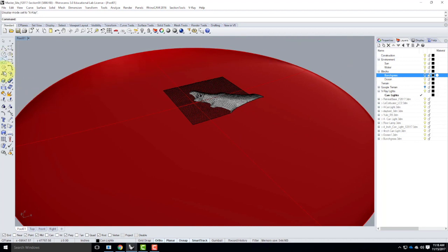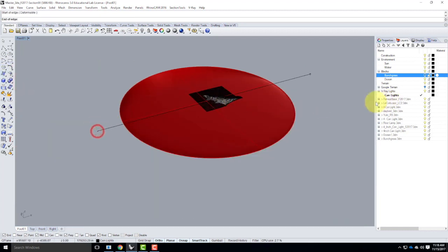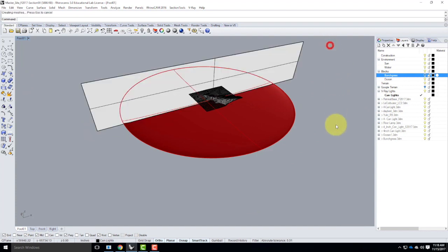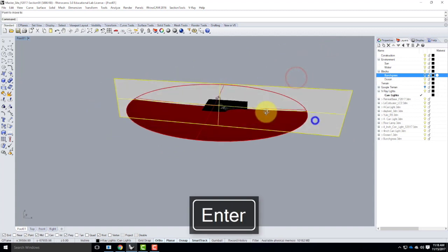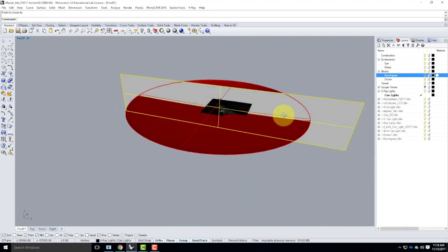section. And so if I went in and I created a tall vertical plane, so I'm going to do a vertical plane, bigger than everything in my model, something like that. I then need to move this down, so I'll move V for vertical so that it clearly intersects absolutely everything in my model.